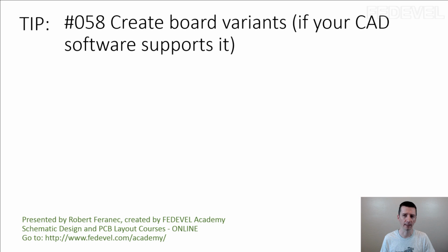You still may think, maybe I don't need it. Yes, if you are working on a project, finishing it and you need to generate the manufacturing information, you can create the variants manually. It's not a problem. When this feature may become very useful is later. Imagine after 1 year you need to do some changes on your board. You need to create a new version of the board, adjust the PCB or schematic, and generate all the manufacturing documentation again. And after 1 year you may not remember exactly why you fitted or unfitted specific components.